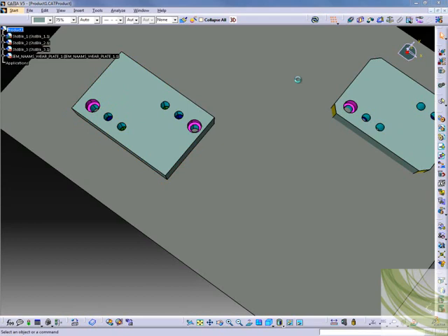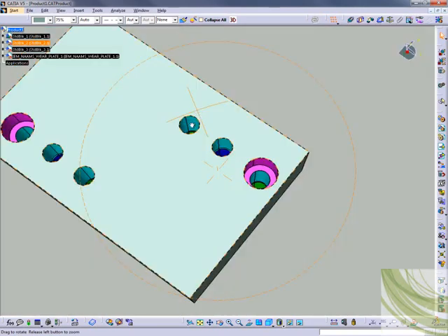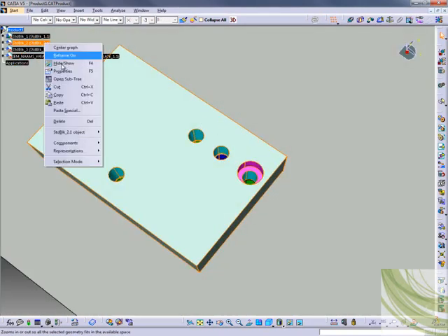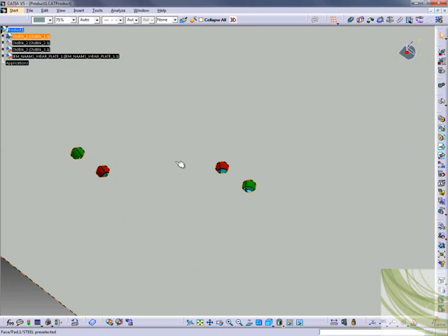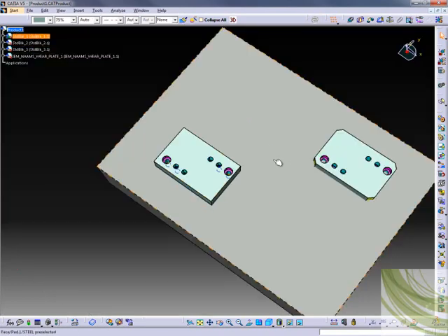And what that's going to do is go through and do the removes for you. So if I minimize this, you'll see we have our screw and dowel removes done in the block underneath. And if I was to hide this block, you'll see them removed there, and those are all linked up, so as we move screws and dowels, they update with it. So that's just doing the one block there.